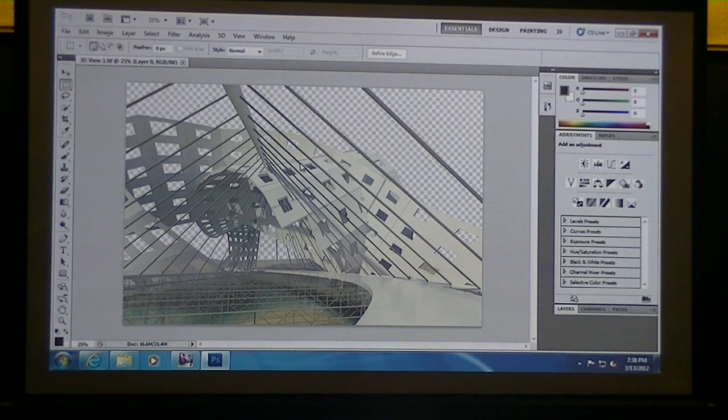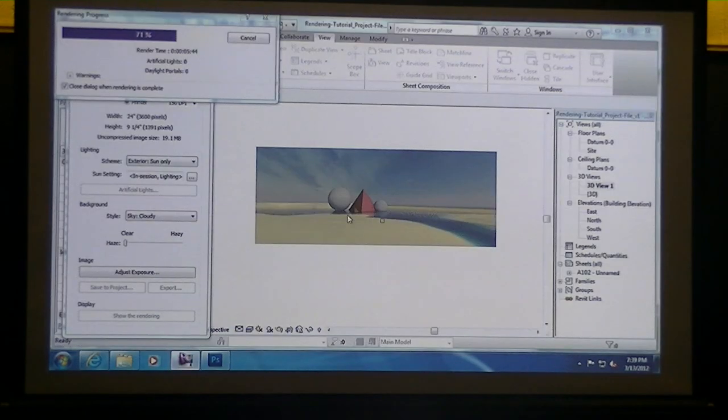That's the nice thing about exporting it as different images: you have that ability, so you don't really have that sky in the background. But just be aware that if you export the TIFF file and expect that you're going to have the sky, you lose the sky. So you have to play around with how you're going to use that image. Of course, when you're done, the rendering that gets saved over here in the project browser is the image that is actually seen here.